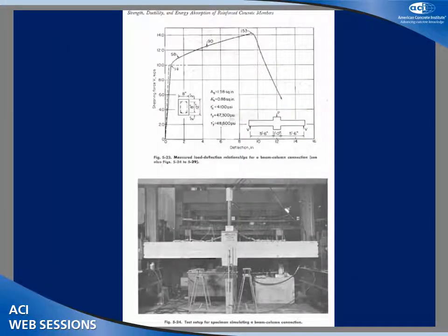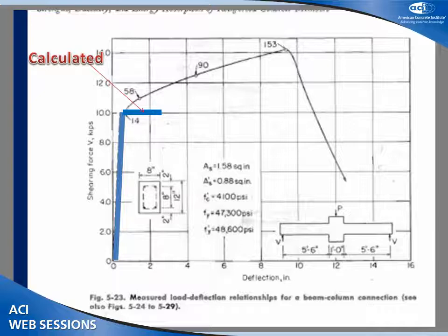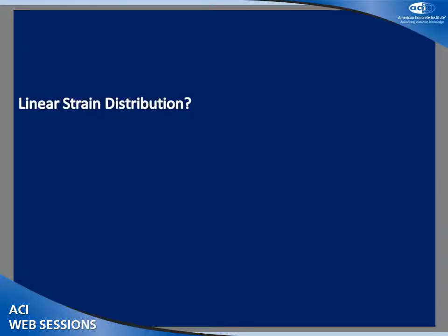But look, I'll take credit for these tests. I designed those tests that several of you talked about. I was wrong. These were irrelevant to the earthquake case. However, they did provide some information. They did provide that our simple Newmark type approach didn't fit reinforced concrete. And first, of course, that you couldn't relate the ductility of concrete to the stress-strain curve in compression. There is no correlation between them. But still, when you see the theory of the time versus the actual behavior, you say there's something wrong. And this was one of the questions that came out of this book, but there wasn't time before the publication of the book to go further into it, so that blue line was left like it was the theory itself.